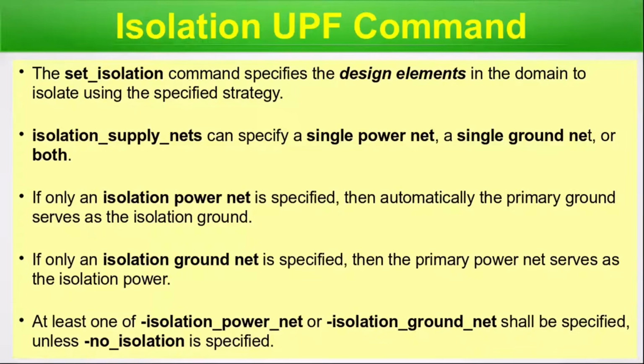So at least one of the isolation power net or isolation ground net switches has to be specified, unless no isolation is specified. So when we are writing this command in our UPF text, we have to specify one of these two switches. This is what we have to keep in mind. Now we're done with this particular slide. So let's move on. Retention cells and flops.